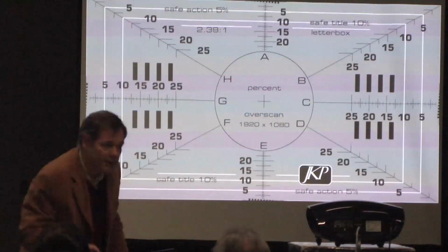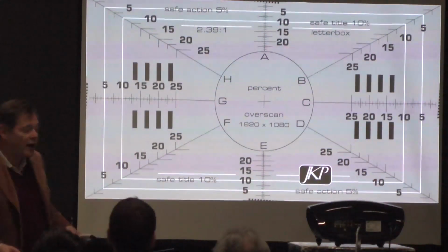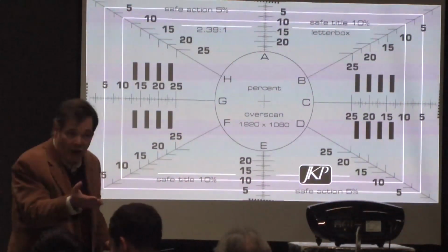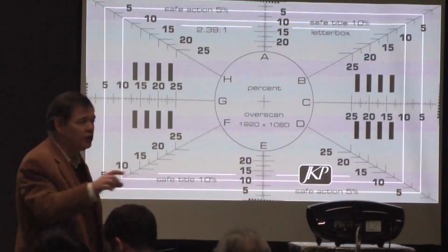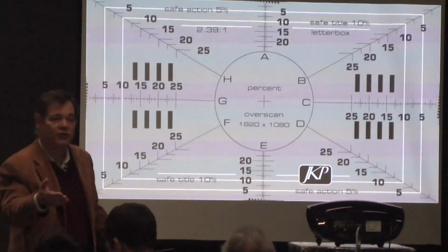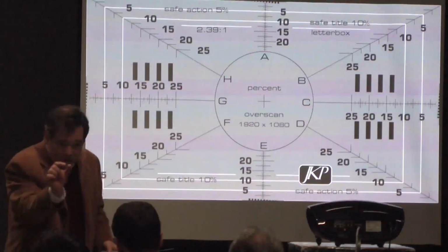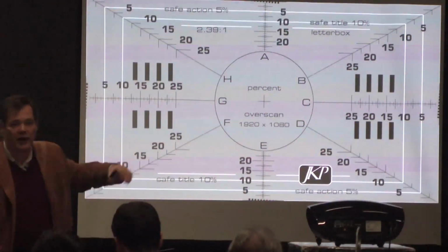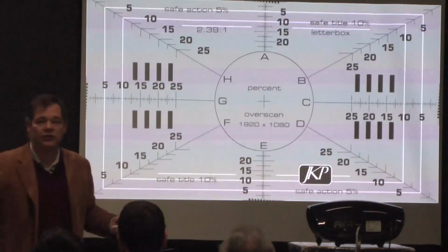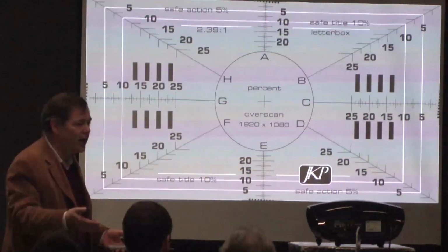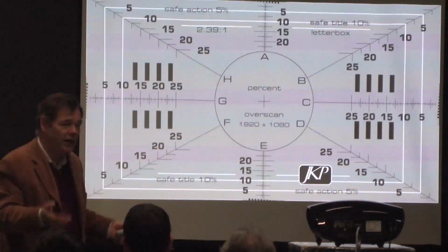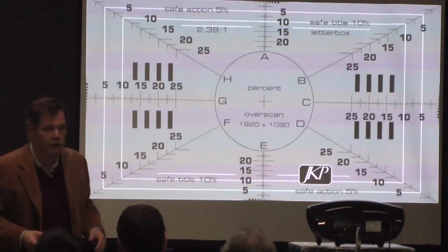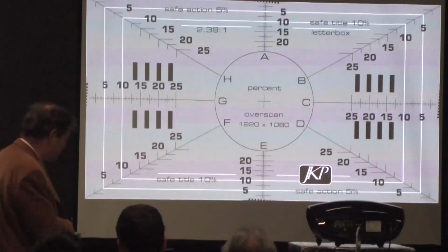Now, regarding the performance of the sharpness control, you will find on some sets that when you turn it all the way down, you can actually soften the picture. So you have to know when the picture is soft. You have to know what the limit of the sharpness control is. It just so happens that for this particular manufacturer, the 0 position is no edge enhancement, no extra edges. So I happen to know that 0 is the right position for this particular projector.